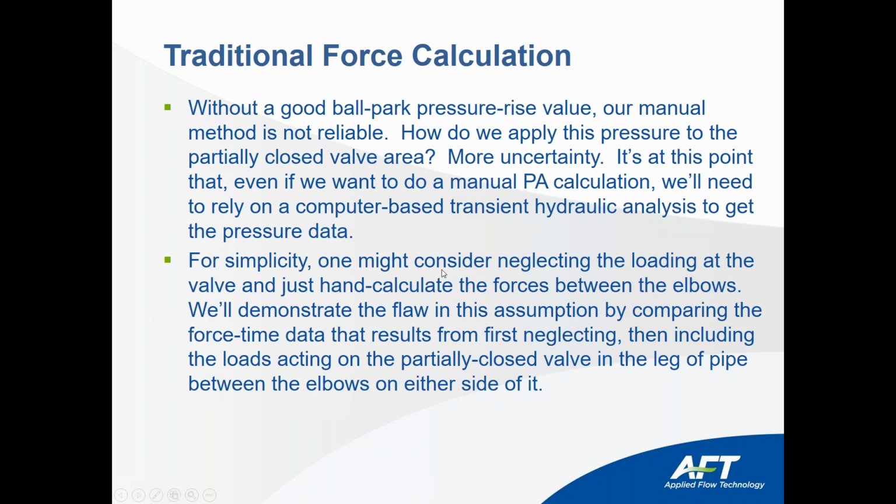For simplicity, one might consider neglecting the loads in the valve and just hand calculate the forces in the elbows. As we saw previously, this is not the best estimate because it would give you high forces that are really over conservative, and you would have to over dimension your supports.